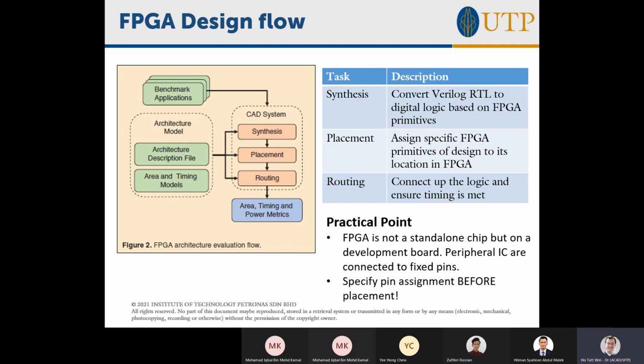I'm going to decide, for an FPGA, where in the chip these resources are, because your FPGA doesn't have unlimited logic primitives, right? It doesn't have unlimited logic units. It's got a fixed number of units, and they are at certain positions around the FPGA chip. So the placement step is just identifying: I'm going to use this one at the top left corner, this one in the middle for this. So it's identifying where to put it.